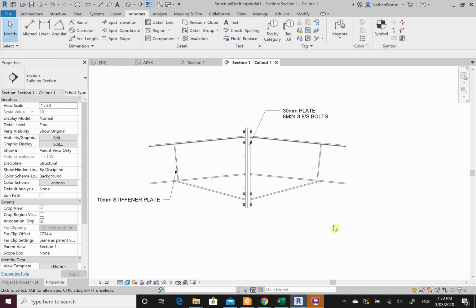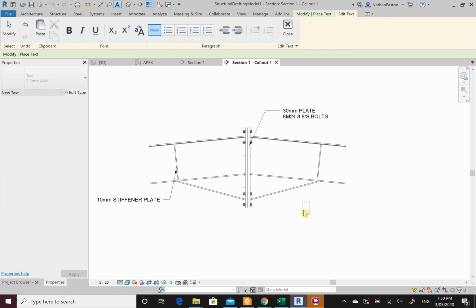So you'll see that when we get to that point, but for now I'm going to go TX, and I don't want a 6 millimeter weld here. I'm going to specify a different type of weld. So I'm going to specify, say, an 8 millimeter. We're going to use a stitch weld. Okay, but the type of weld that we're going to use is going to be an intermediate fillet weld. So an IFW, which is a stitch weld. So an intermediate fillet weld, so they'll weld a section, then they'll stop, then they'll weld a bit more, then they'll stop. That's going to be a general purpose weld.